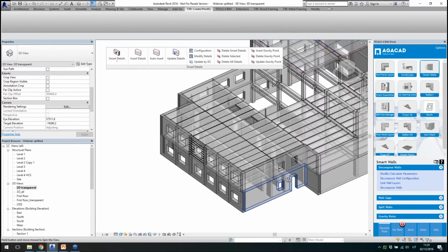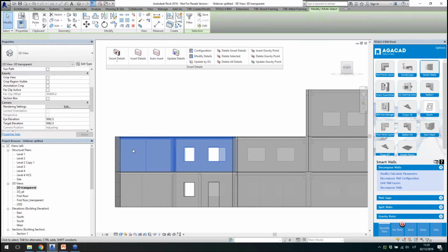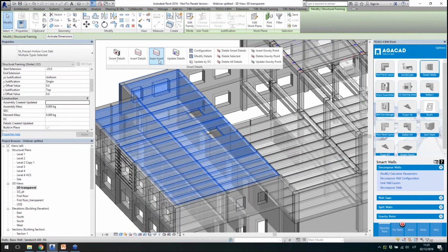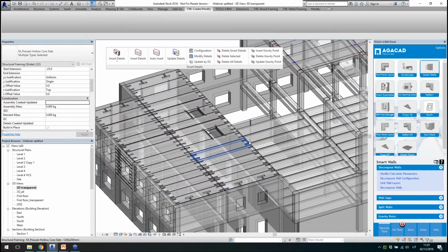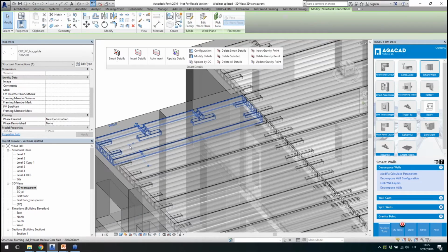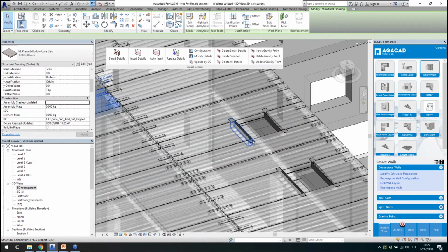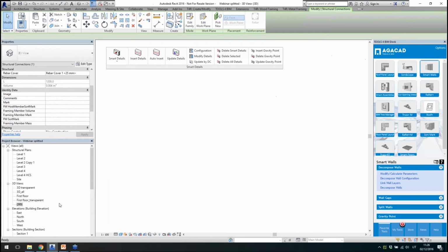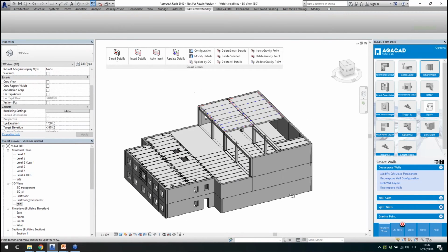And you can use that in different ways, and I can just show you a couple of more examples. Like I will select these, right, and just structural framing elements, and I will just auto-insert. Auto-insert just reads the configuration name in the properties of the element and uses this configuration. So let's say in this case, I have these elements inserted like a cut. I have some supporting elements as face-based elements on the top of these slabs, and so on. So I can just prepare different kind of configurations.